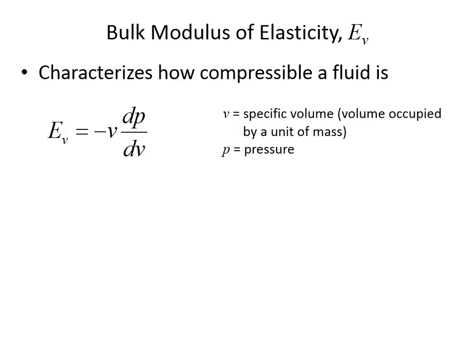So how do you do these calculations? The types of questions you ask in a water hammer problem are: how big is the shock wave going to be? What's the pressure you can expect? Because you want to know if the pressure from the water hammer is going to exceed the capacity of the pipe. Another thing you need to know is, how slowly should I close the valve? It turns out that if you close the valve more slowly than it takes the water to go through one round trip, then you'll avoid the water hammer.